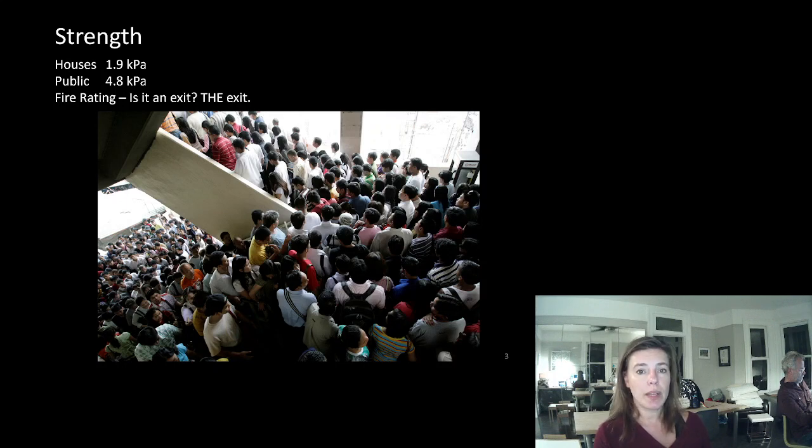And that can be really important because some of the fire rating criteria means that you have to be kind of encapsulated or separated from the rest of the building, which you can imagine for a feature stair, which is out in the open space, you don't want to then drywall it in. So that's why you might need other exits, and then that stair might not need to be fire rated.